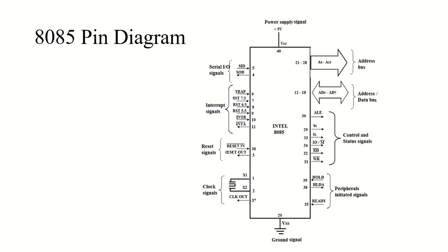In the previous class when we discussed the registers, I told you that I will be discussing the flag register in upcoming time. So I want to discuss the 5 flags of the flag register. So let's get to it. Basically a flag is a flip-flop. It indicates some instruction executed by my microprocessor. The flag register of 8085 microprocessor consists of 5 flags,